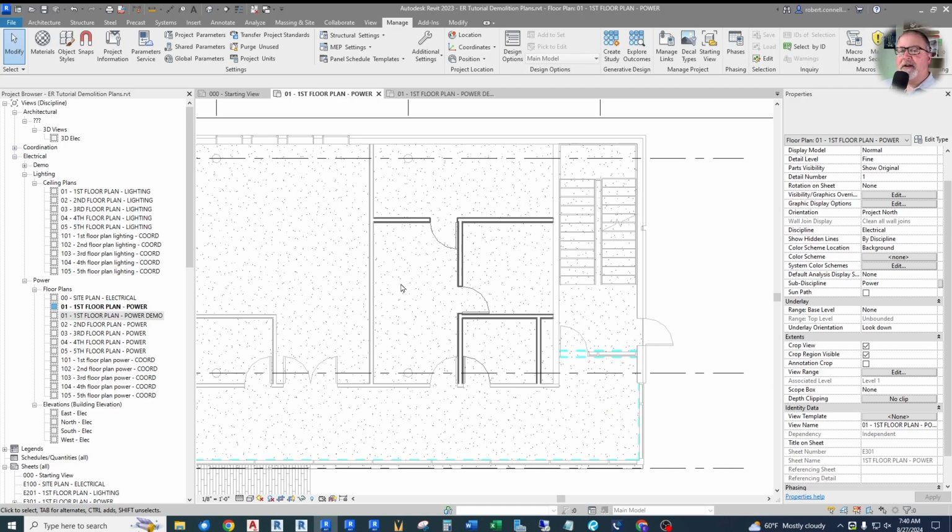Well, Revit has a built-in project phasing system, which lets us identify for each piece in our model what phase it was created on and what phase it should be demolished on, if at all. And then has a set of filters and graphic overrides to change the appearance depending on the status of each of those pieces in the phasing. So let me jump right in.